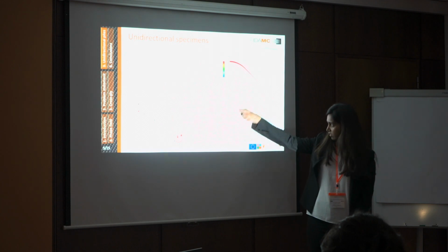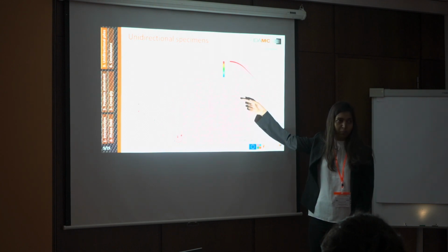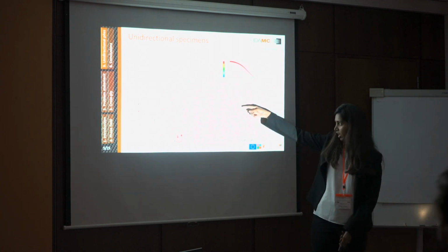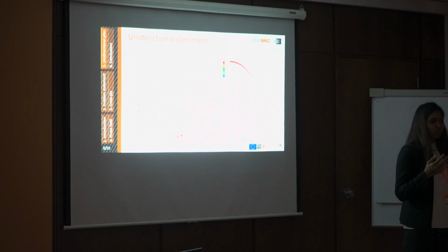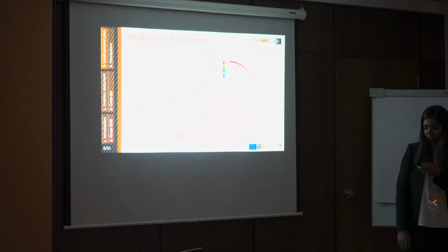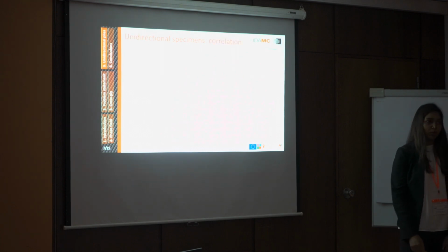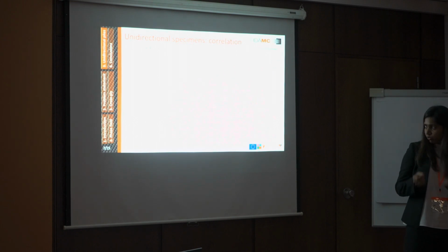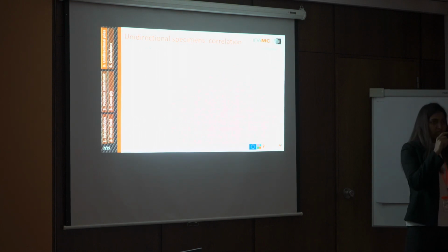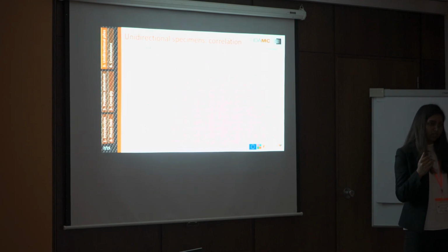The moment increases linearly until a certain point, which is the peak value, and suddenly it drops, representing a very unstable propagation. So in order to capture this instability, we have used a control algorithm approach by Professor Emilio Martinez-Pineda. What we do here is we introduce 2 auxiliary nodes at the crack tip opening, and then we control the model using the crack tip opening displacement.